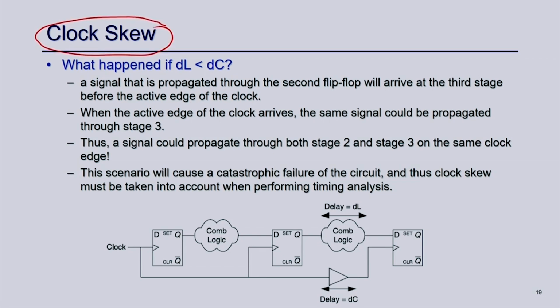What is clock skew? The same clock is feeding all the registers of your circuit, right. Suppose your circuit has only one clock, not multiple clocks. But our expectation of a synchronous circuit is that that particular clock will reach all the registers at the same time, right. If that happens, there is no problem, but in reality that may not happen, because of some delay, as we discussed about clock gating, and even the clock path has to route through some routing. So, it may not happen that the clock reaches all the registers at the same point in time. There might be some delay, and that is what is called clock skew, right. It is the difference in time between the clock arriving at one flip flop and at another. So, that is what is called clock skew.